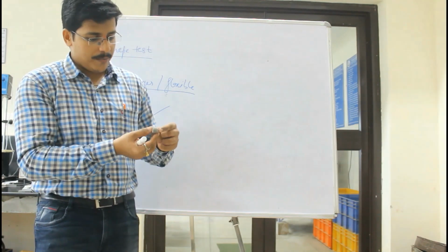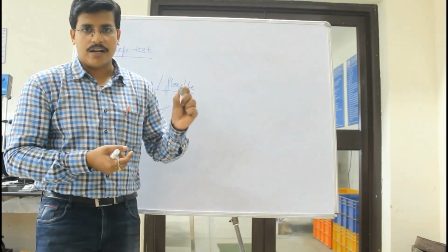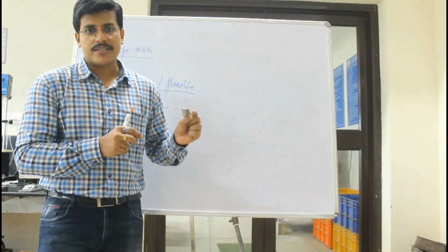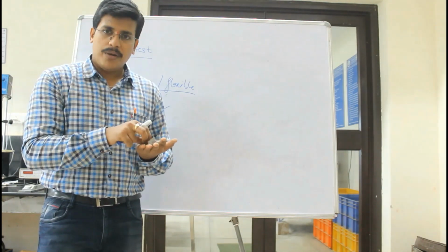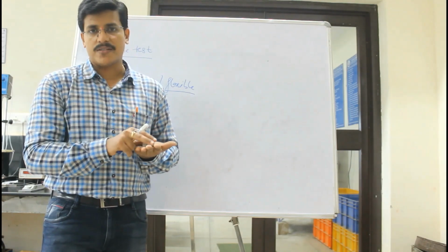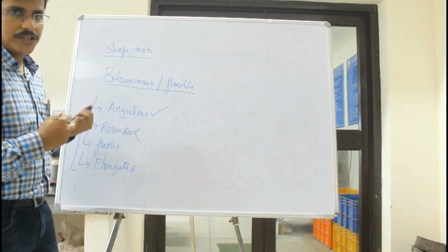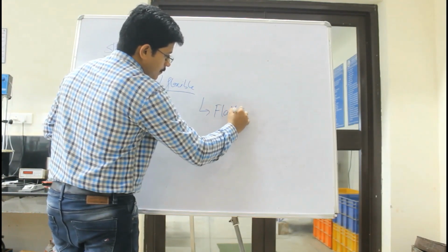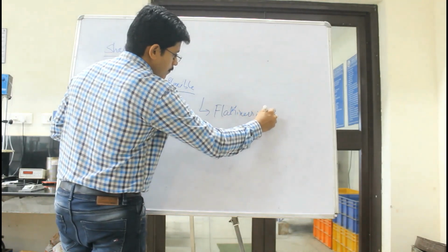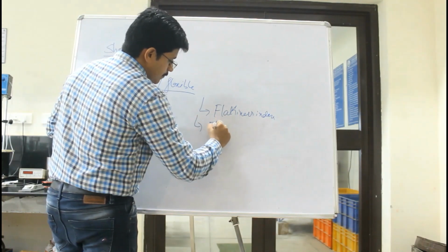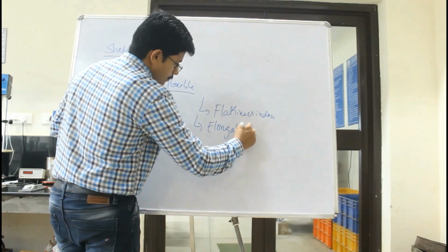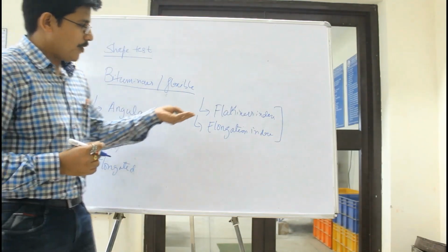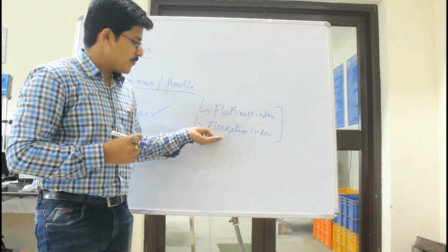But this particular aggregate is a typical angular or cubical aggregate where you can expect very good interlocking during its service life. This way, the aggregate shape plays a very important role in the mix performance. So to determine the aggregate shape, we conduct two tests called flakiness index and elongation index. From these we determine the percent of flaky aggregates and the percent of aggregates which are elongated.